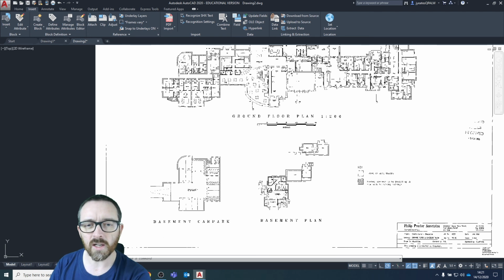We can actually scale these drawings so that they become one-to-one, and that's going to be much more useful for us. So the model space in AutoCAD, all of your drawings in there should be one-to-one, and then you can adjust the scale on different layouts in different paper spaces, so that you could then print and share that information with other people. Okay, so this is going to become clearer as we use AutoCAD more.